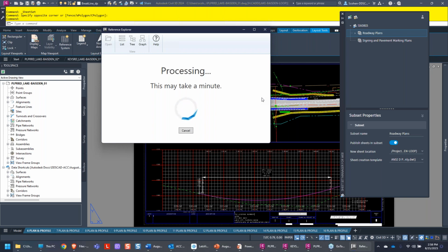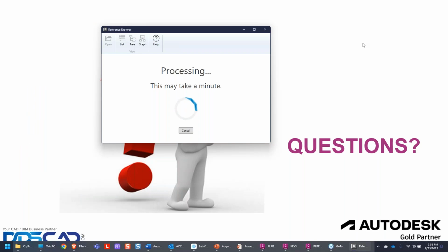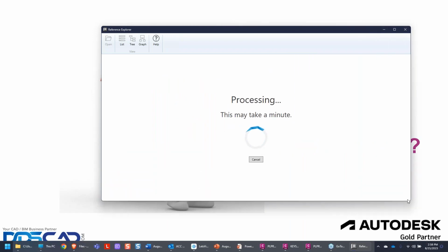And then what you're going to have to do is go into each file and change the way that existing file resolves the references, okay? So basically what this should do when it's done, hopefully it won't take that long, it's going to show you AutoCAD references, data shortcut references, template references, fonts. It shows you basically almost everything that you will have referenced.